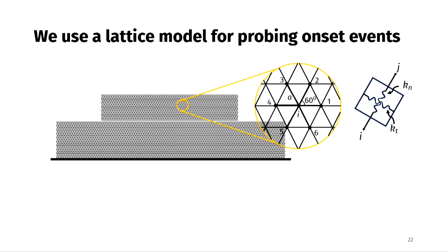Okay, and you need both of these because you have to fit two elastic constants, the Young's modulus and the Poisson ratio. So this allows you to do that. But if you had just one spring, then the Poisson ratio will be fixed for a given Young's modulus and a given lattice orientation. Now we can fix both independently by changing these two parameters.